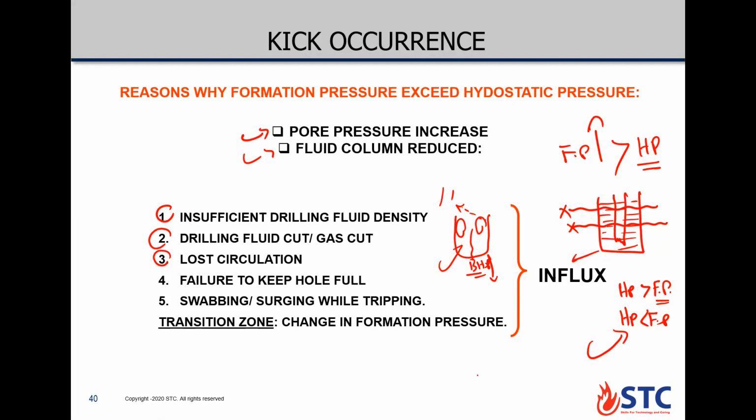For example, let's say formation pressure is 3000 psi, and you drill here with your mud weight to overcome it, giving you hydrostatic pressure of, for example, 3300 psi.